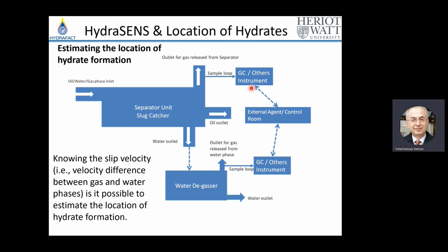What happens to hydrate? Hydrate density is very close to the density of water, so it will fall into the water phase, and we look at the gas released from the water phase. First of all, the amount of gas should be increased because hydrate stores a lot of gas, but also here you should see a high concentration of C3 and IC4.